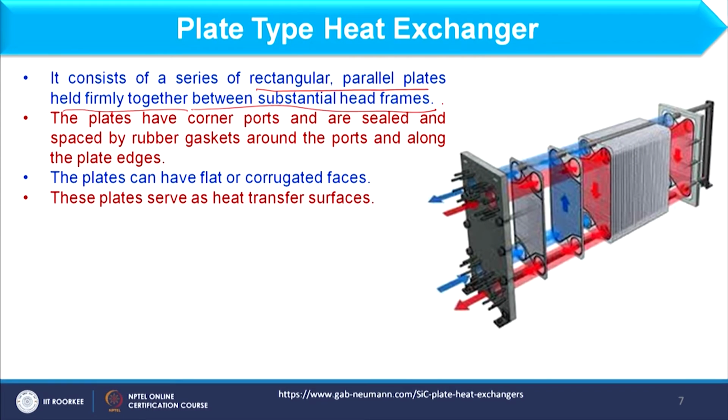Fine. Now if you see this schematic, this structure, okay, this rectangular plate and this bar, okay, and if you see at the top we have this bar also, okay, where these plates are hanging. Okay. So this bar is available at top as well as bottom, both sides. Okay. So each plate type heat exchanger has plates which are arranged parallel to each other like this and this, and it is held firmly together with a substantial head frame.